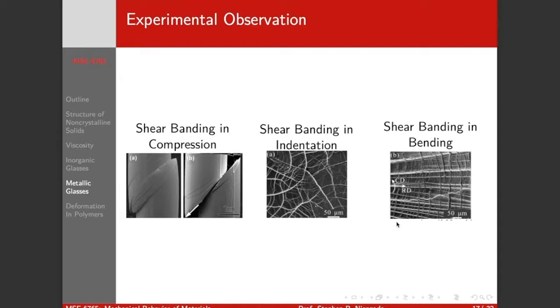you have crystalline regions and amorphous regions. So you get the high strength from the amorphous region, but the crystalline region deforms easier plastically and allows you to get some more ductility. The crystals basically block the shear bands from propagating all the way through, and they diffuse the intense shear within the shear band by activating multiple slip within the crystalline regions. And by doing that, you can get some significant ductility out of metallic glass systems.